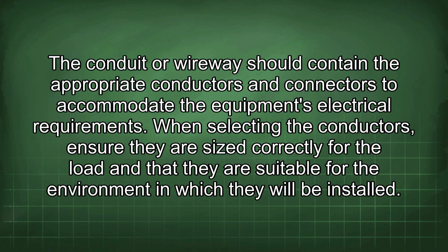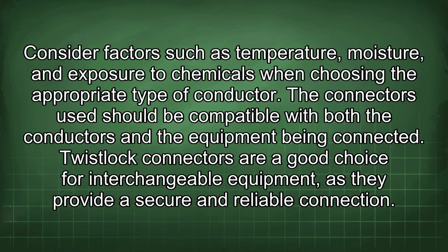When selecting the conductors, ensure they are sized correctly for the load and that they are suitable for the environment in which they will be installed. Consider factors such as temperature, moisture, and exposure to chemicals when choosing the appropriate type of conductor. The connectors used should be compatible with both the conductors and the equipment being connected.